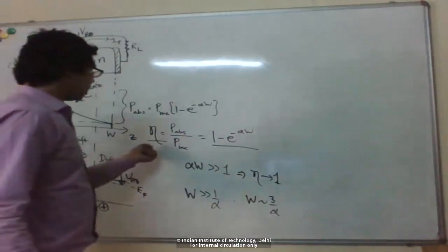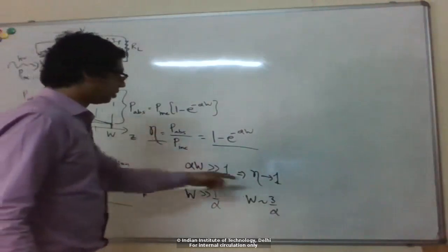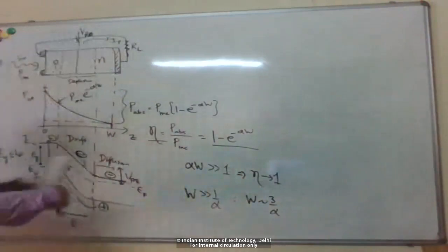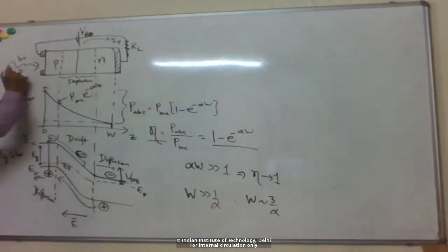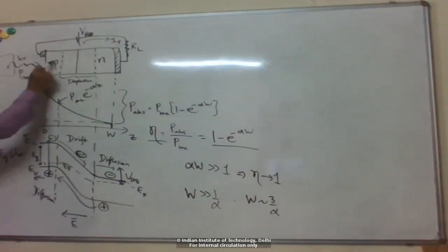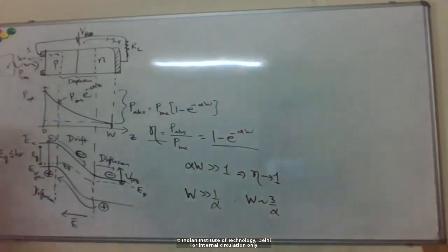Okay, and there is also one other thing that can reduce your effective quantum efficiency. Imagine there's an optical fiber here, and the light comes out briefly into free space and then goes into a detector. Here you have a refractive index of 1, whereas in the detector you have a refractive index of about 3.4. So there's a huge mismatch, and you can get a huge reflection at the input facet. You might lose a lot of light just due to reflection at the input facet itself.